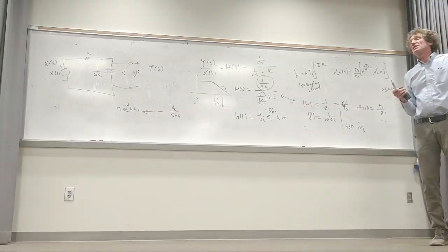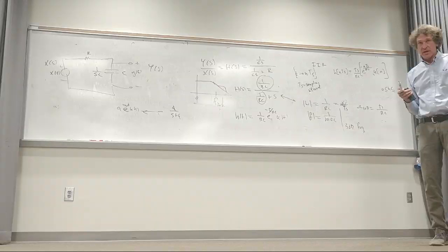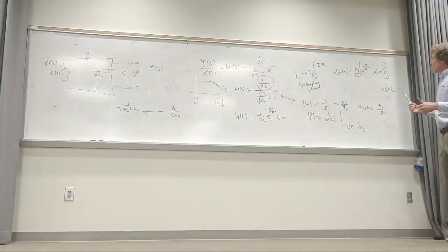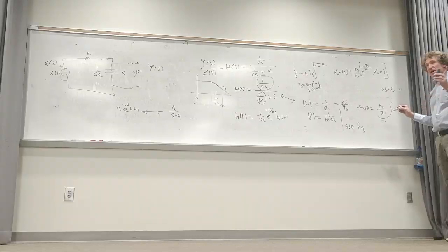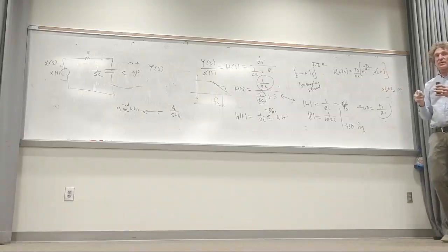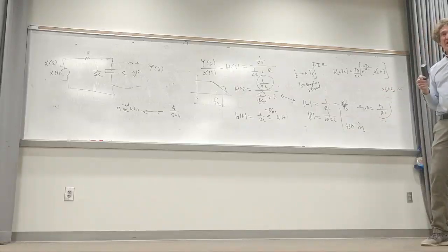The frequency I had in the omega domain for that was what? It was pi over 2. Do you remember that? That's for capital omega, right? Capital omega is like small omega times TS. Now, for this one, the 3 dB frequency would be TS over RC. But when you take this filter output, sampled right here, this is 20, and you take, say, 11 points here, just 11, if you try to do this without a window and do convolution of the original signals we had, we could adjust it so that the 3 dB frequency would be, in fact, pi over 2.